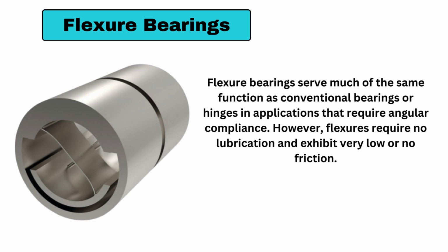Next bearing is the flexure bearing. This flexure bearing we use for special applications. Flexure bearings don't require any lubrication and provide very low friction.